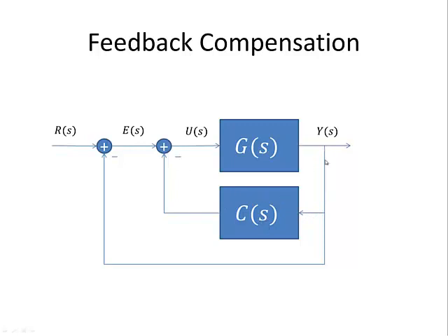In this architecture, we're using the output of the plant, and we have a feedback compensator, or control law, but there's also an outer feedback loop, which compares the reference to the actual output of the plant, which generates the error. This architecture is also known as inner loop control and is often used for aircraft or autopilot designs where the feedback here is actually working on, say, aileron position, but the actual reference might be pitch angle.